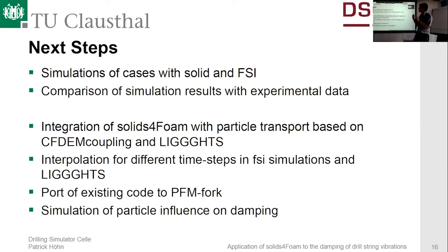And what is still different in my current code, it's not perfect as usual. One limitation which I still have: right now I don't have any interpolation in terms of time step for the movement of the solid mesh compared to the particle movement. So right now I need to couple every CFD time step to every DEM time step, which certainly is not the way to do it. But that's something I would also work on when I'm working on the integration again.